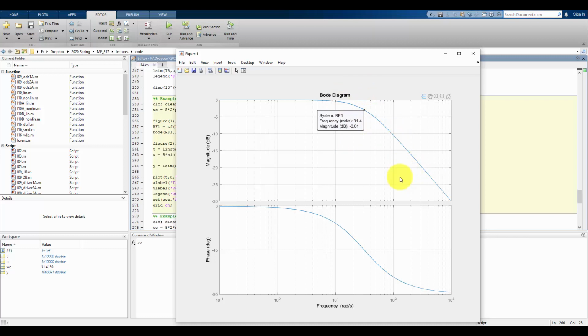So something we just want to be aware of is, one, just because we're below the cutoff frequency doesn't mean there's going to be no attenuation. We see that we can have up to -3 decibels of attenuation, and maybe those are some of the signals we want to keep. And just directly after the cutoff frequency, we're not completely getting rid of any signal that is at those frequencies. It's going to take a little bit of time before we can really tamp down on those things that are happening above the cutoff frequency.